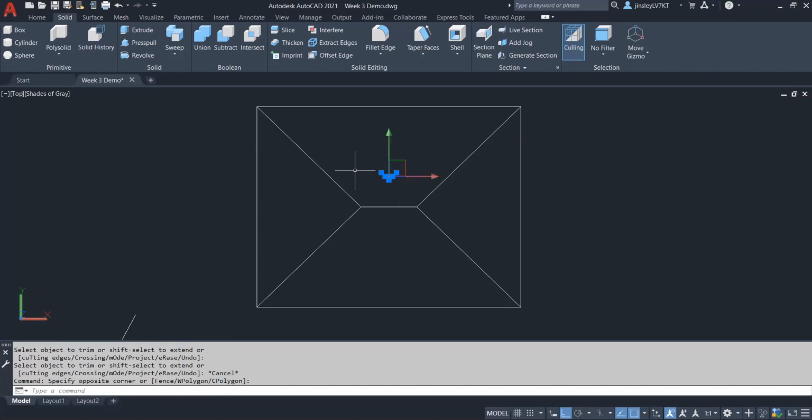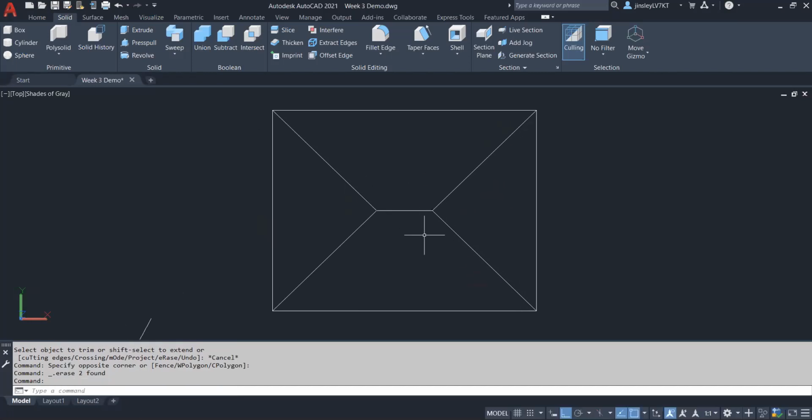Okay. So in plan view, what the architect provided me, I have this simple roof plan. You'll know the slope, so we'll know the specific height to model it to. And the way that we would model this is we would trace out each of these shapes as a polyline. Okay, there's my polyline 1. I'm going to be lazy and just do this twice, because technically we could just flip them to the other side. Okay, there's my second polyline.